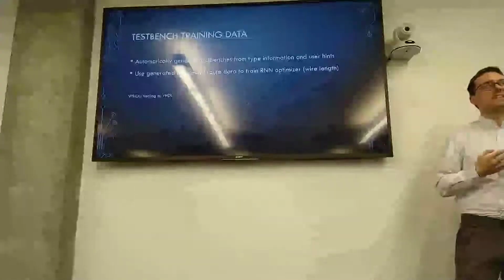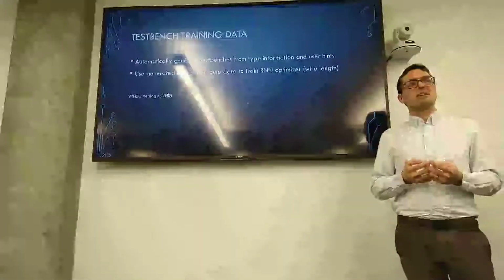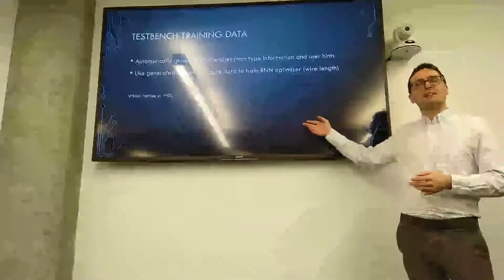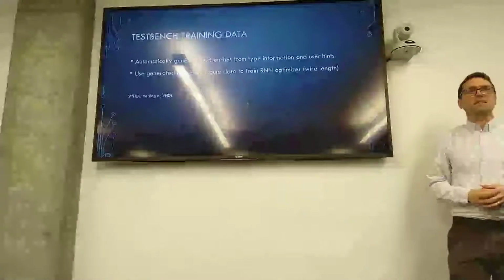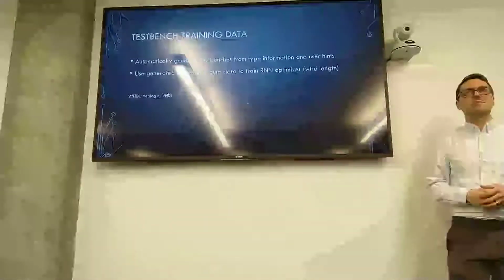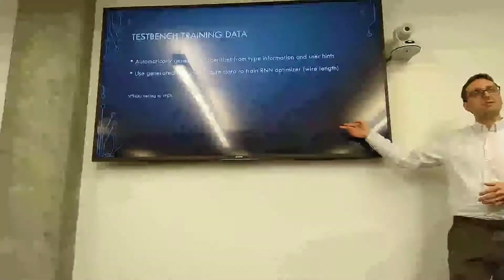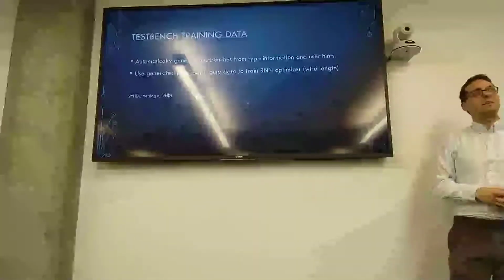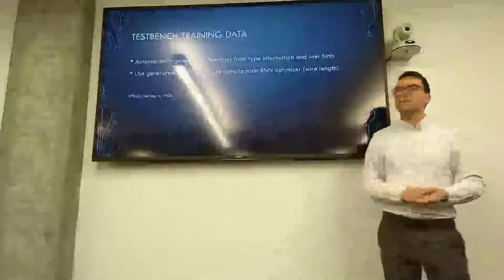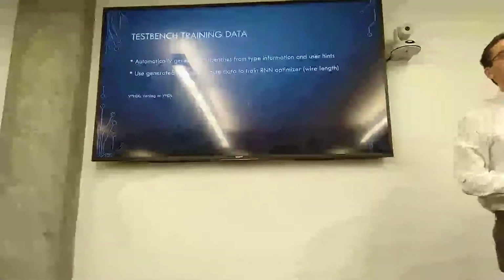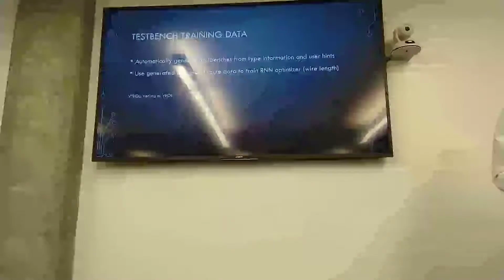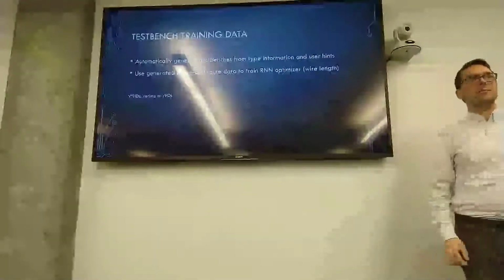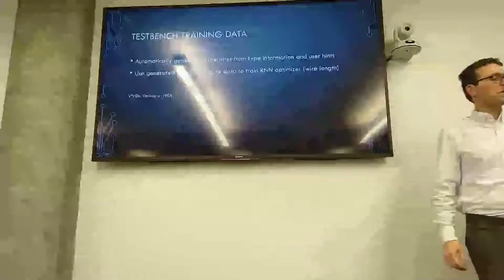And using generated place and route, which is typically not part of a test bench, my idea is to also automatically do some place and route as part of the compile. Using that generated place and route as training data for some recurrent neural network will give us a way to see which optimizations are more useful than others.